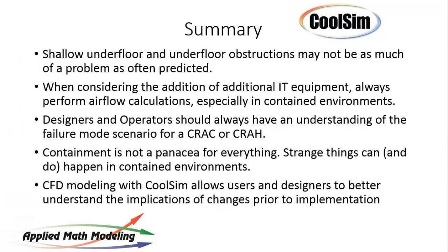Generally, I encourage hot aisle containment because one of the things I notice in cold aisle containment is that the room becomes the return, and when somebody enters the room who's not aware or comfortable with what you're doing, they'll immediately start changing thermostat temperatures, particularly if it's a colo. I know situations that are cold aisle contained where they'll reduce the temperatures when the customer comes, and then when he leaves, they'll turn them back up. It's just kind of silly to me.